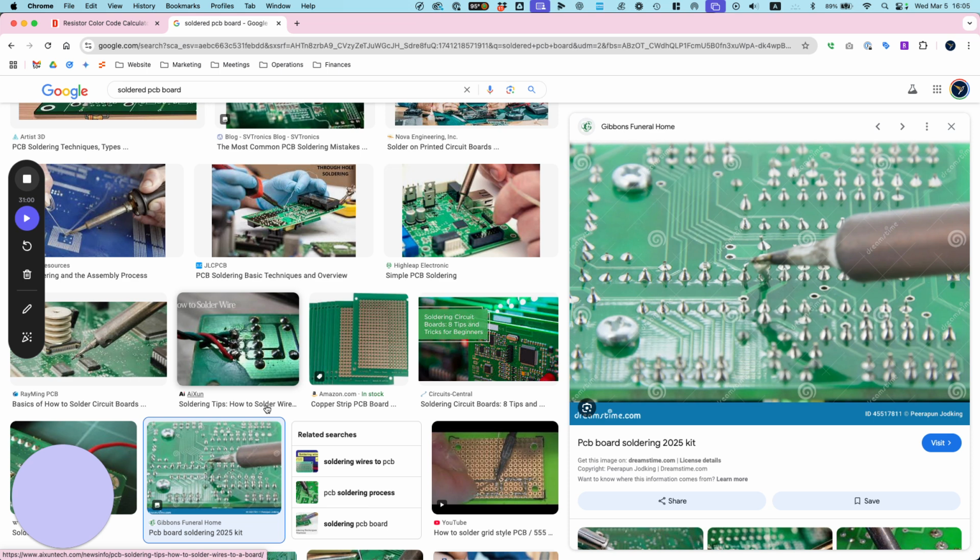Okay. And then an electrical circuit, like we have here, has a switch, load, power supply, and conductor. That's in very basic terms. We actually don't have a switch on this. The switch is just you plugging it, unplugging it. But you can imagine it's a switch instead. We have our load. The load is any component you have on here. So the LEDs, the resistor, those are your loads. Then we have our power supply, this thing. And then we have the conductors, which is really your wires and your solder. In this case, the solder, like a river, is kind of like your conductor. It's connecting all of those devices together.